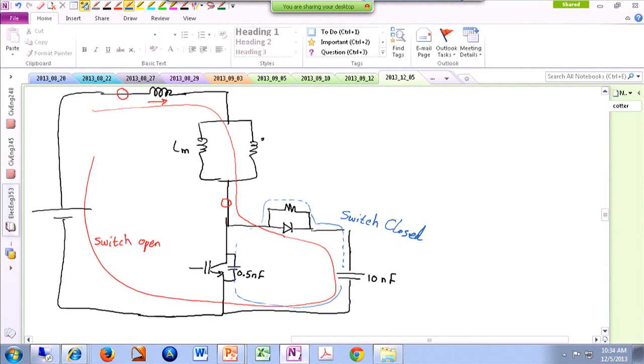So when you open up the switch, in order to hold the voltage to a certain tolerable value, you add this external cap, and the energy stored over here is going to charge up the cap. And then when you close the switch, this energy should be released somewhere. Part of it will be released in this resistor, and part of it will be released in the internal resistance of your switch. So you can see you're actually adding a little loss to the system, and for what cause? To actually protect your switch.